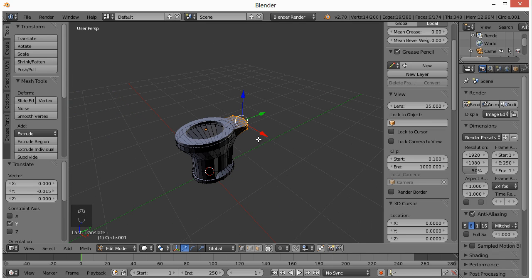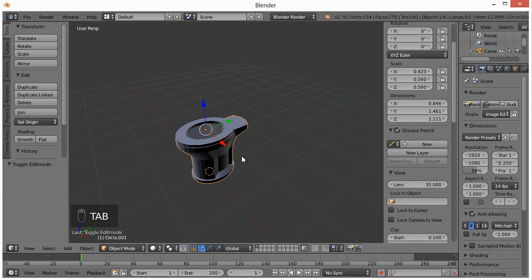object. So whenever you go, say for example, if we added an object right now and hit Shift A, that would end up adding the object to this current object right here because we're in edit mode. So tabbing into object mode and then adding a new object will add a new object and won't be connected to any other objects. Just a tip there.